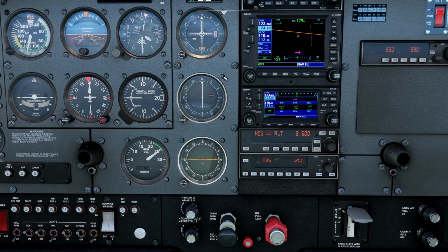Okay, so let's take a look at the vertical speed hold mode and the altitude capture function. Again, the vertical speed mode is the default pitch mode when the Autopilot is initially engaged, and the altitude hold mode select button toggles between this mode and the altitude hold mode. You know you're in vertical speed mode when VS is enunciated in the pitch mode display. Once you activate the vertical speed mode, the pitch trim buttons can be used to adjust to the desired vertical speed, and then you have to manually control the power during the climb or the descent.